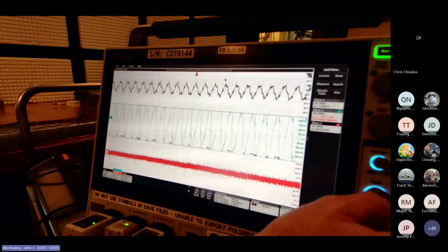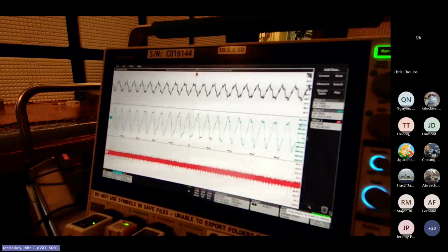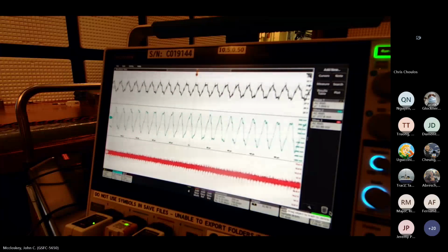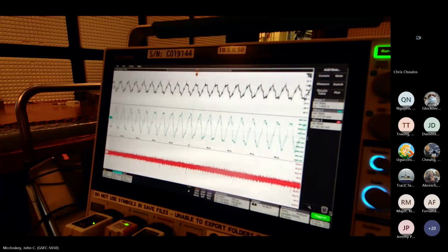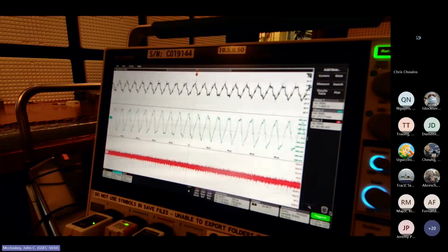Okay, let's all right, the current's gone up noticeably. So our input impedance has gone down. So this is at 100 kilohertz. Signal level is minus 25.5 dBm. So we're sitting right around a volt AC RMS.